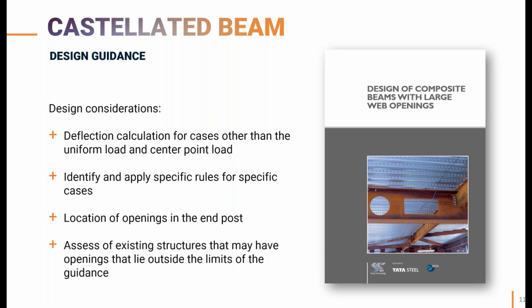We also need to carefully consider the influence of openings at the end posts at the high shear zones, where besides the high shear forces, there is also potential interaction with the type of the connection. Lastly, in case that openings are created in existing structures, there is always the danger that these openings may lie outside the limits of the guidance due to accidents and construction failures.